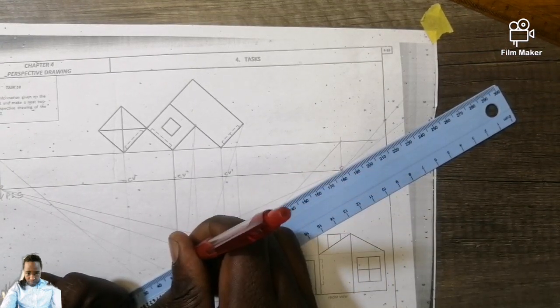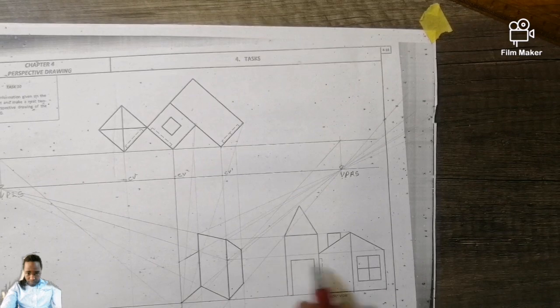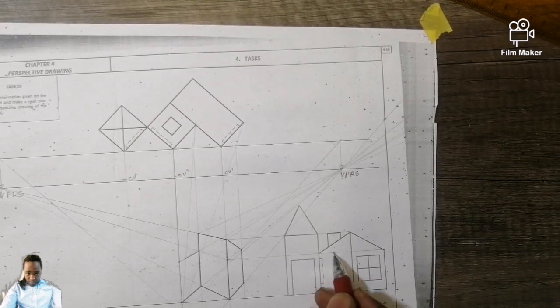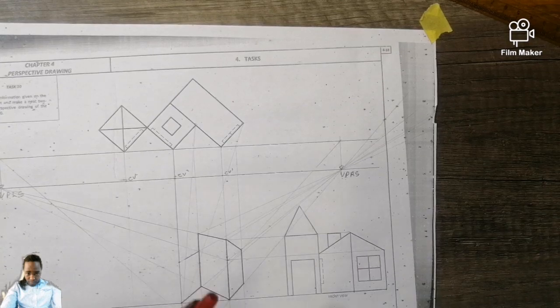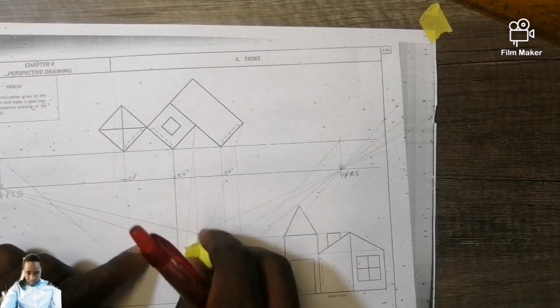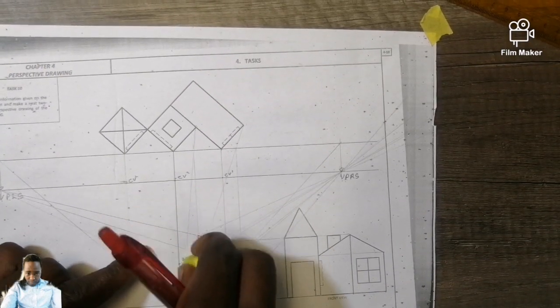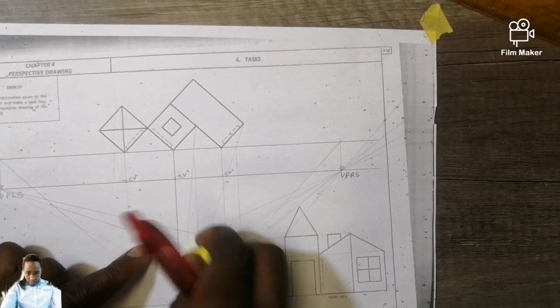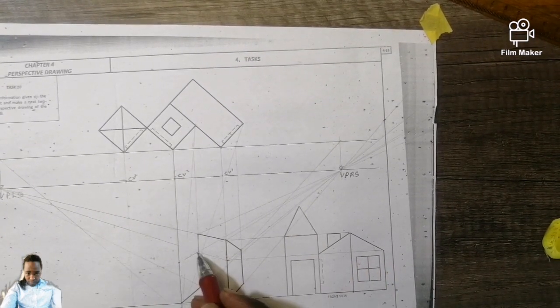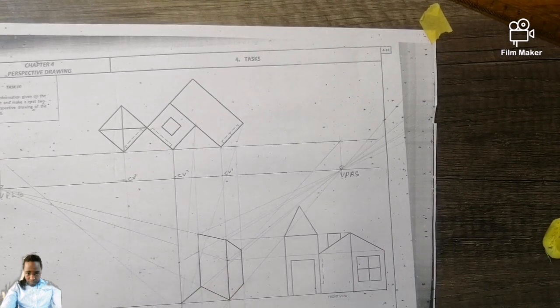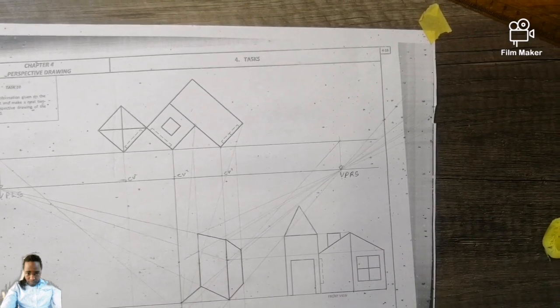Hey, what am I doing? Because I do not have a solid line here. So which means again here I cannot have a solid line. Erase it, it is still early. You understand? I do not have a dark line from here till there. So same applies from here till there. I cannot draw it dark.